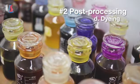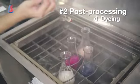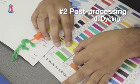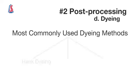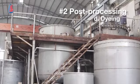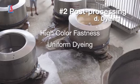Dyeing. Before the mass dyeing, professional color staff will prepare the color formula according to the customer's sample and dye it with a dyeing machine. Then, they compare the dyed sample with the customer's sample under the specified lighting environment. After confirming that there is no color difference, mass dyeing will be carried out. Hank dyeing, dope dyeing, and cone dyeing are the 3 most commonly used dyeing methods. The dyeing method used in our factory is hank dyeing. Compared with other dyeing methods, hank dyeing has the characteristics of high color fastness and uniform dyeing.